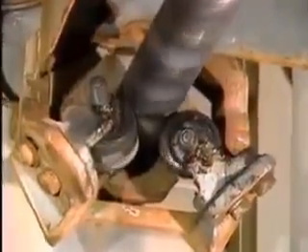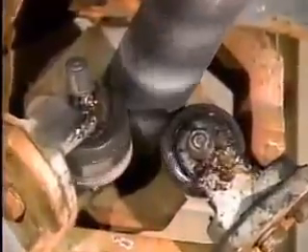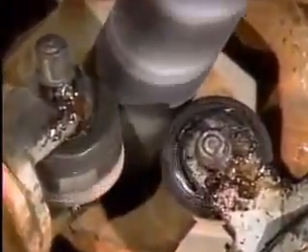The rollers support a device that's used to clean the tubes inside an operating boiler. Heat from the boiler is transmitted to the rollers and the grease. Grease made with ordinary thickeners would melt and drip out of the bearings, but the bentonite resists high temperatures, so it keeps the grease from melting. Many substances that are added to lubricants are liquids rather than solids. Some of these additives reduce friction under conditions of extreme pressure, such as between gear teeth.